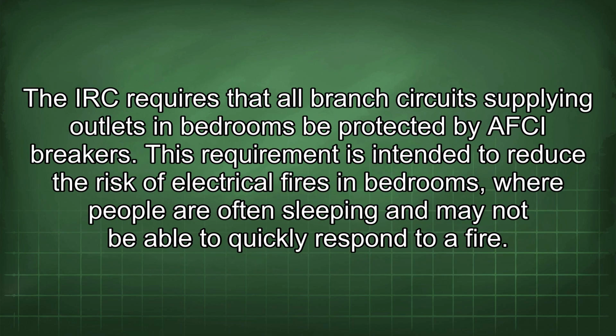The IRC requires that all branch circuits supplying outlets in bedrooms be protected by AFCI breakers. This requirement is intended to reduce the risk of electrical fires in bedrooms, where people are often sleeping and may not be able to quickly respond to a fire.